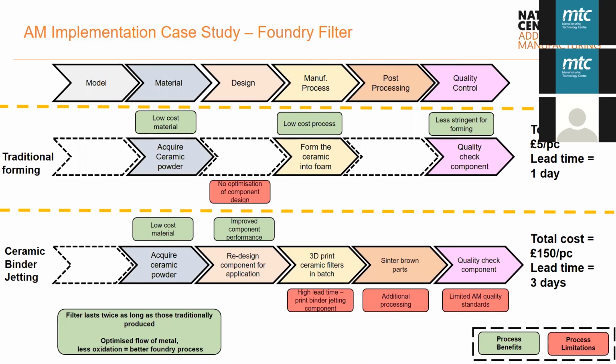So how do you take care of distortion in powder bed fusion, and is it good to have a heated build-up plate option? Specifically when you're building small height parts? Yeah, so there are some systems that offer a heated build plate, which significantly reduces the amount of residual stresses. The residual stresses come from thermal gradients in melting, and you can get rid of them through heat treatment mostly. You can reduce them in build also by support strategies. So you have more support to the base plate, thicker base plates, that kind of thing, it will hold it in place. And then heat treat after printing to remove those stresses.